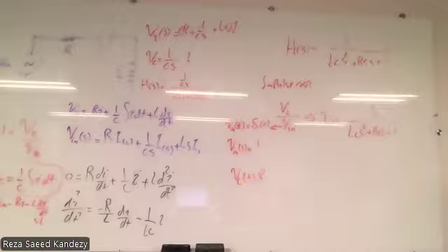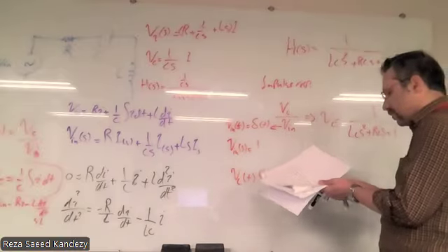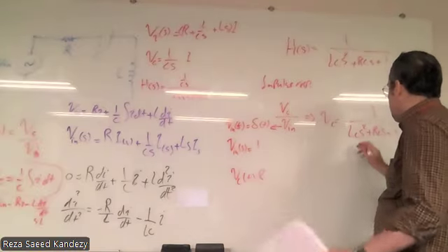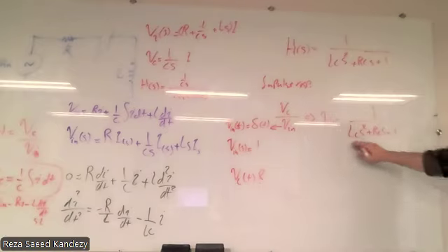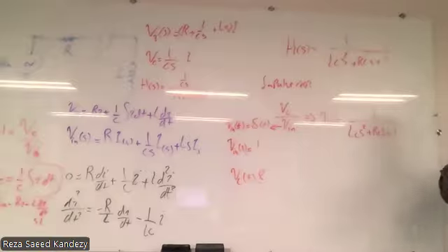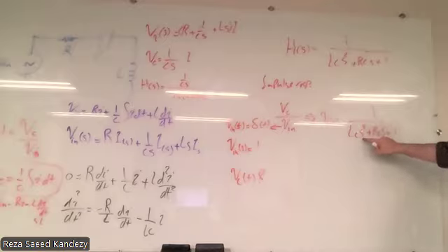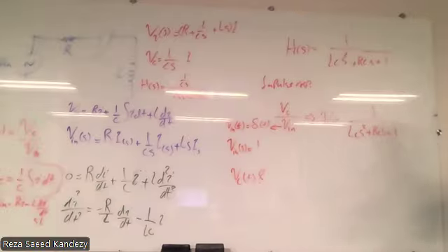that means what we need to do is to turn it in a way that this transfer function becomes the Laplace of a sine function or a cosine function or both. Does that make sense? Now, how we do that is a little bit of mathematics here. Let's simplify the notation and the indexes here, and make it a standard second order equation. The standard second order equation means that the second order term coefficient should be 1. This is a standard way.